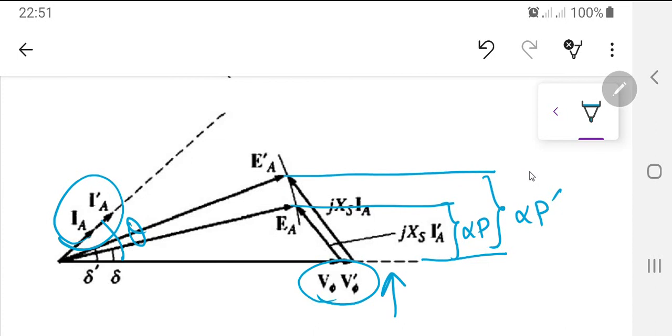So you can see the Y component of the EA vector is increasing. This means the load on the generator is also increasing, but since this was a capacitive load, the phase voltage is increasing. Now in this case, if we want to remedy it, and you have a capacitive load, which by chance is not going to be there unless you deliberately attach capacitors, because capacitive loads are normally not found in load centers or anywhere else. But still, if you have to remedy it, the only way possible is to decrease the field excitation, that is the rotor DC current flowing, IF, so that you decrease your V phase.